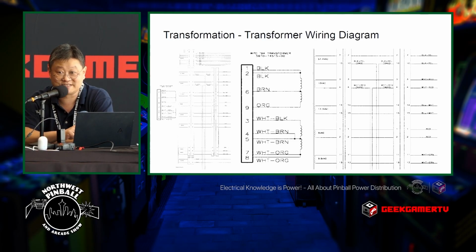The center tap is the key. You ground the center winding, you tie the center winding to ground and cause one of the windings to go on the negative side and the other winding to go positive. This is why I can't emphasize it enough. The reference point is what matters.